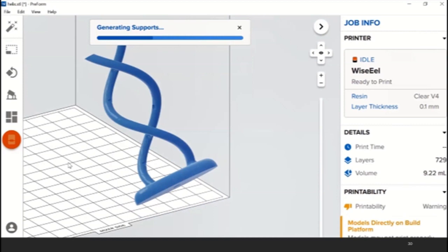So, it's really up to you. More users most likely just customize their own later on, but for beginners, this is really good to start with. And you always most likely will do it at a 20-degree angle, or something like that. And this is because it's trying to reduce the surface area per layer, just to reduce the peel forces that I mentioned before, and to make it a nicer, smoother finish overall. So the software is doing all the work for you in here.